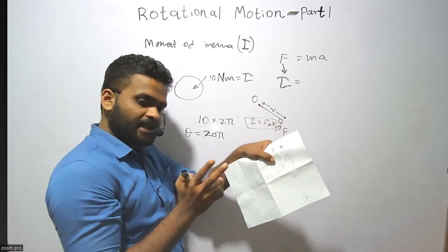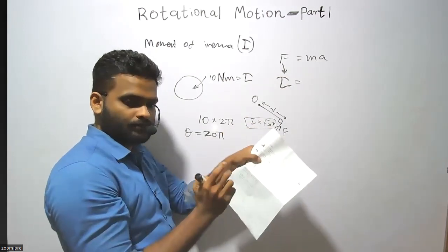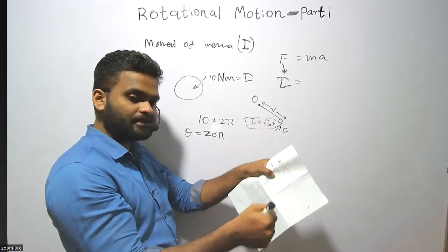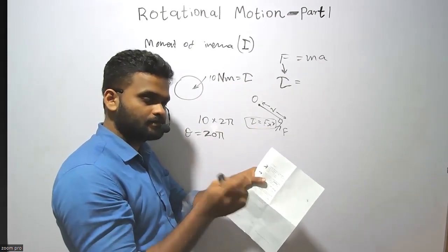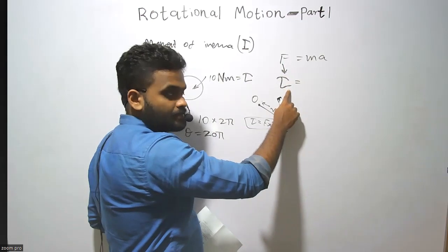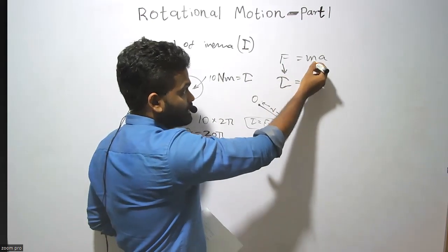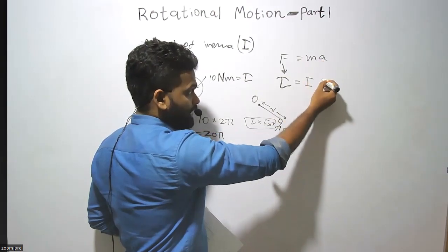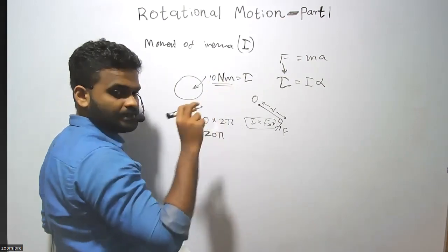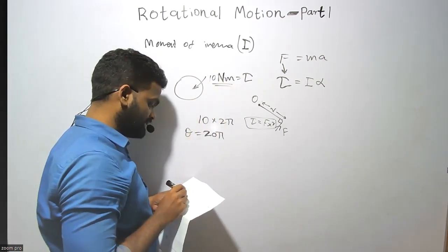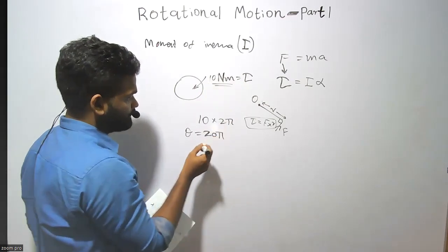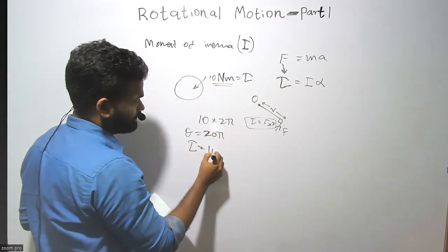To make a rotational motion, you need to apply a torque, not just a force. To rotate objects, you always need a torque, or we call that moment. Remember moment, not momentum. So instead of F you have the moment, or torque. Instead of mass you have I, and instead of a you have alpha. In the question, it should be corrected as torque 10 Newton meter.